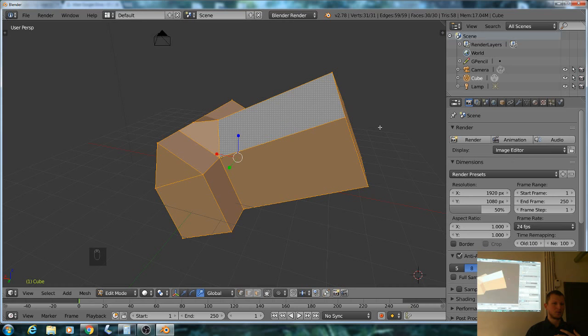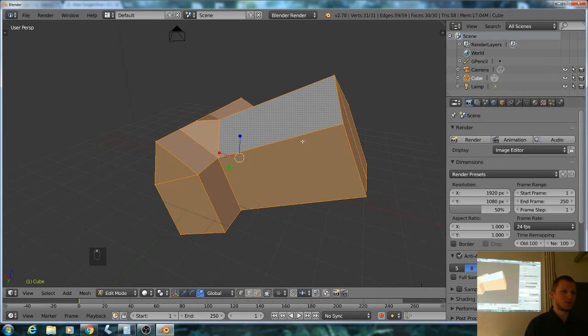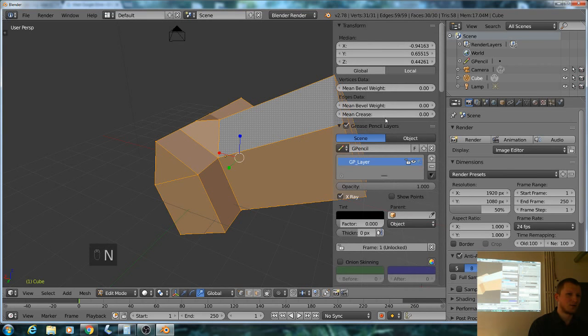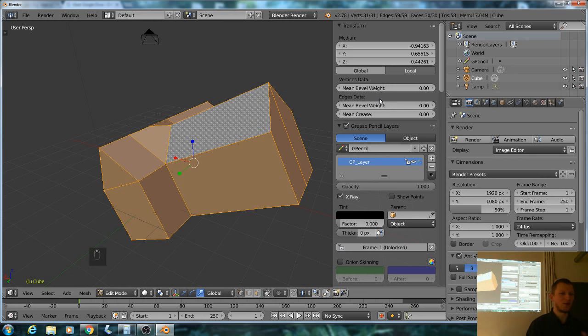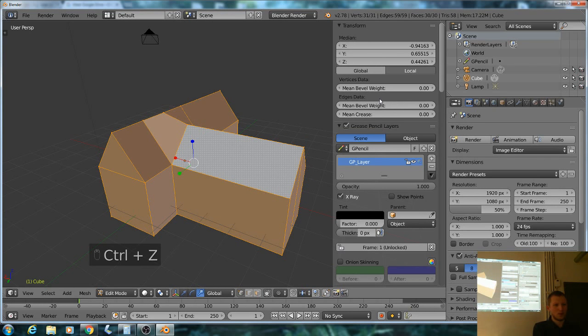So basically, if I rotate it, I can't take it back, because there isn't a rotational value, and there is no scale in edit mode. In edit mode there is only the position of the vertices, and if I want to take it back I have to do it with undo, and if I don't have any undos left then I just can't take it back.